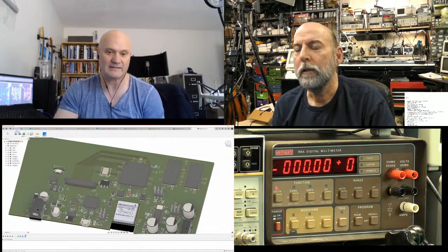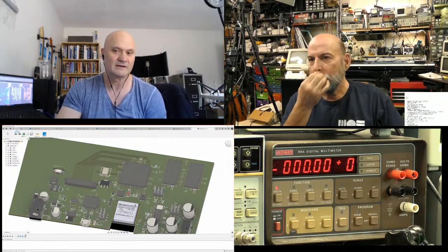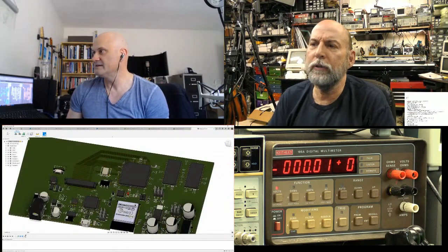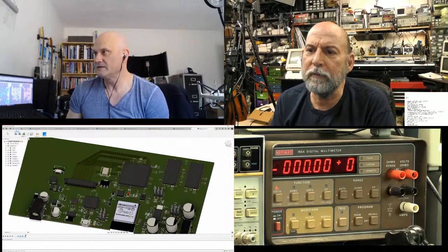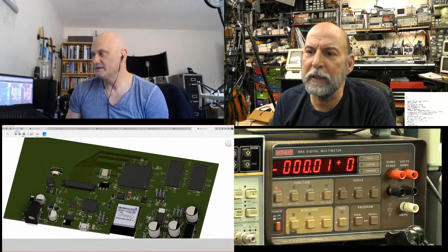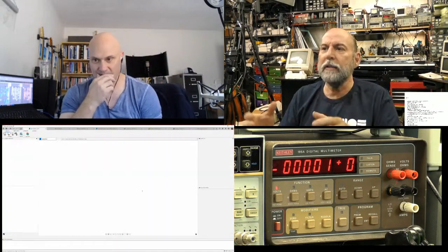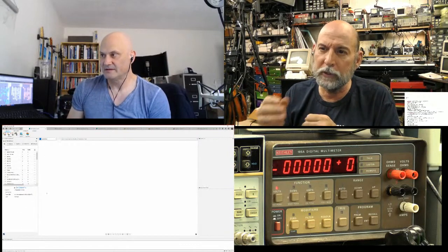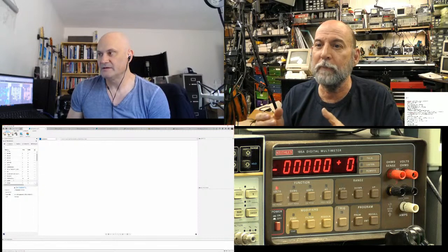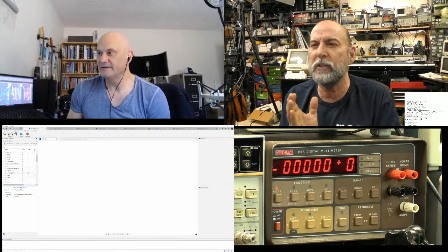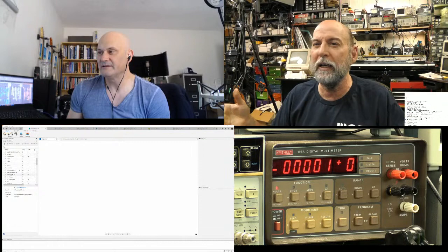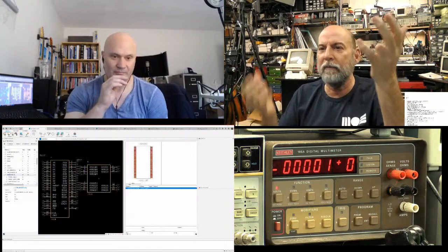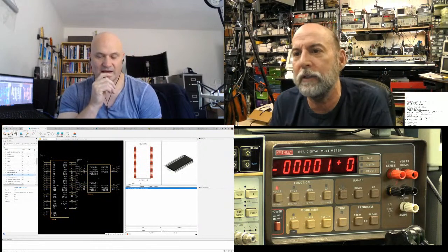I mean, that's kind of where things like ULP scripts come in to automate the process. Right. Now, I used to do a floor planning stage. I would do what you did, but then I would stop and go ahead and compile the FPGA a little bit to see if I'm going to be able to hold to that pinout. Because there are sometimes where you just can't get all those functions on one side of the chip, or you get almost to the end and find out you can't fit it. So you have to do some floor planning, layout, and kind of guide yourself through it.